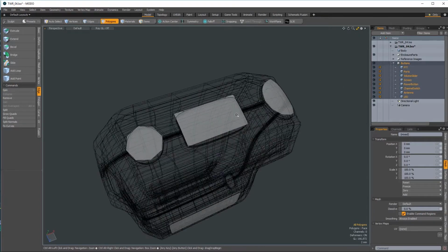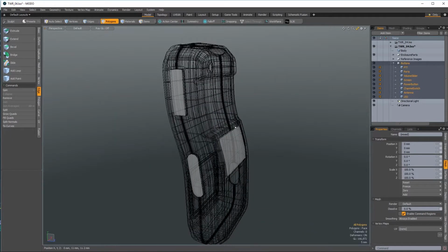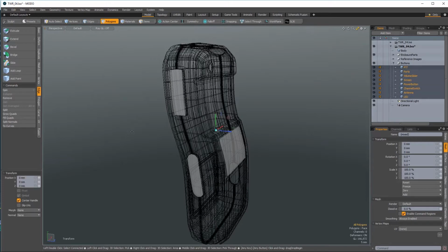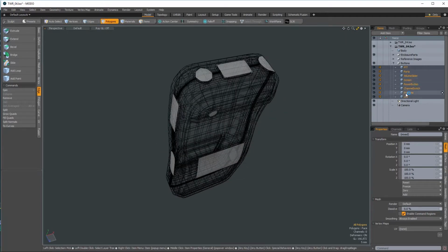The first thing you'll notice is that they are slightly off center, and that happened when we moved the front part of our enclosure forward by 3/4 of a millimeter. So let's move the buttons 1/2 of 3/4 of a millimeter. So I'll activate the move tool by hitting W, and let's just punch in 0.75 divided by 2. And that should move everything back into place.